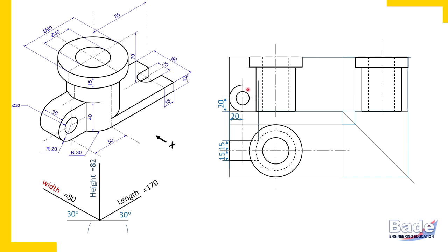Along this projector corresponding to this corner you should draw the edge, and the U-shaped block, that is this front U-shaped surface, meets the curved surface, and where it meets the curved surface it creates a sharp edge. So the exact location of that edge we have identified here.